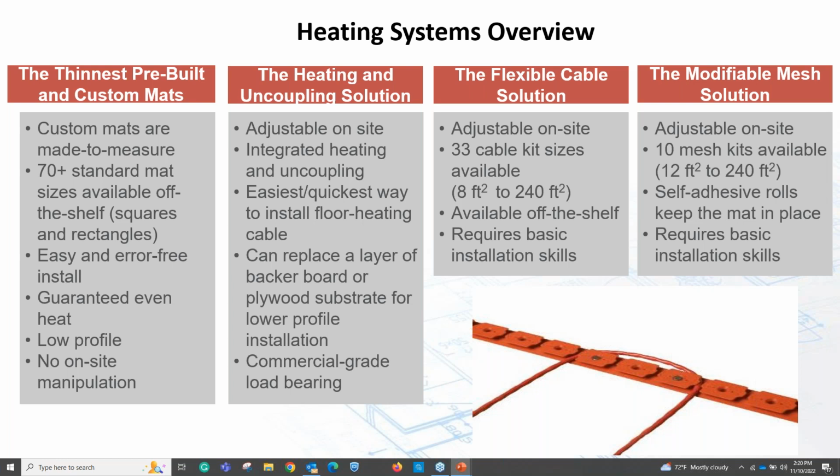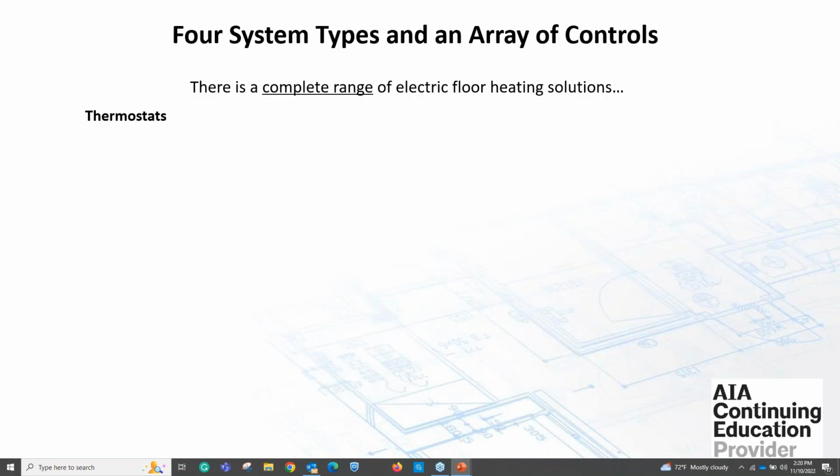Then you have your old school way, which is your old flexible cable, which I started with many moons ago. You just use cable guides, put your cable out and pour floor level over the top of those. It's still a viable way to do it. And there's some mesh systems out. We'll go over each one of these, to let you see what's out there.